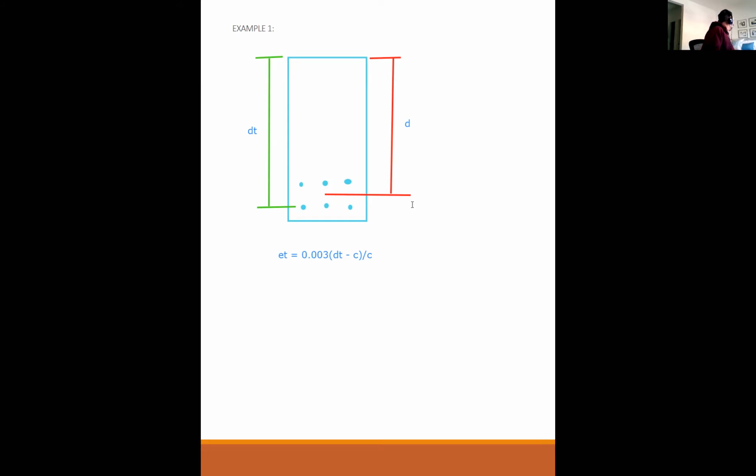Homework problems 1 and 2, where you have a T-beam, on the left side of the T-beam I drew a dimension line and labeled it 31 inches. That is d sub t. It's a little tough to see. It's not meant to be to the bottom of the beam. It's telling you what d sub t is. And then on the right-hand side, you have 3 inches plus 27 inches. So d on the right-hand side is actually 30 inches. I want to make sure everybody saw that and was not confused by what is what.